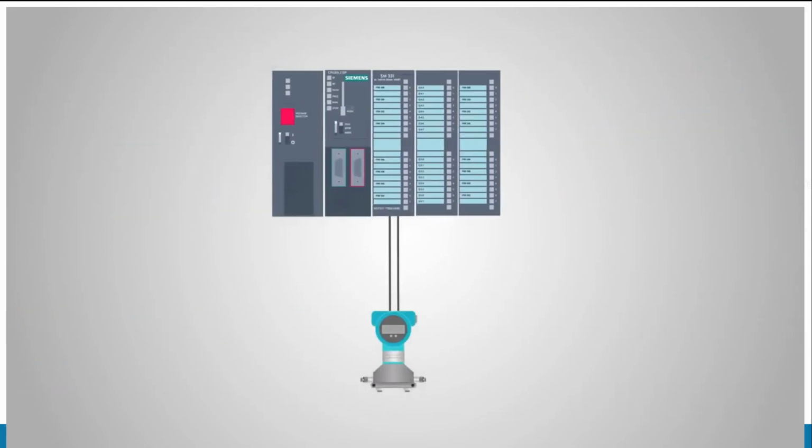Each Hart device is capable of sending and receiving 35 to 50 different information items, including the process variable, that is the same measurement value as provided by the 4 to 20 milliamp analog signal, device status, diagnostic alerts like sensor value under range, basic configuration parameters like upper and lower range limits, and the tag name of the device.